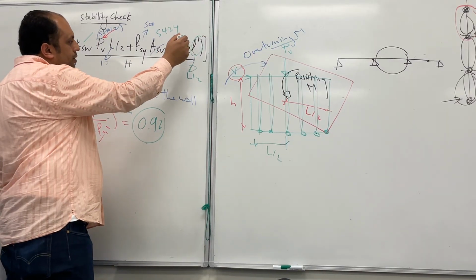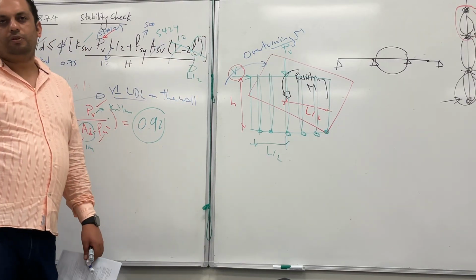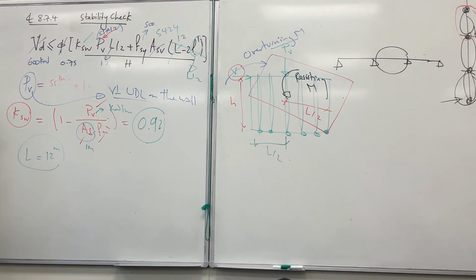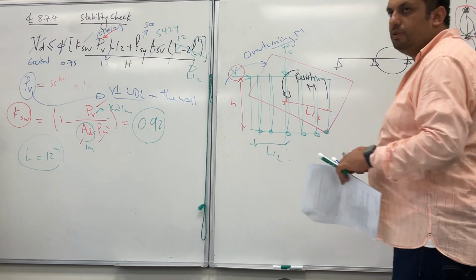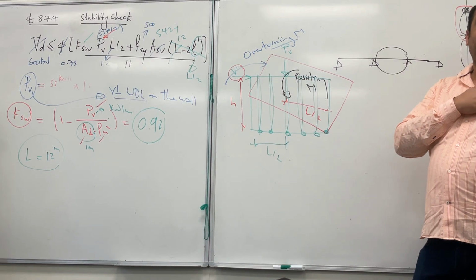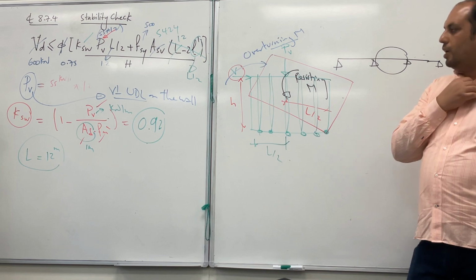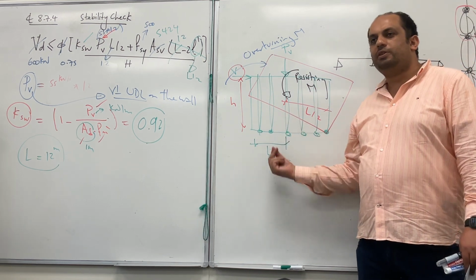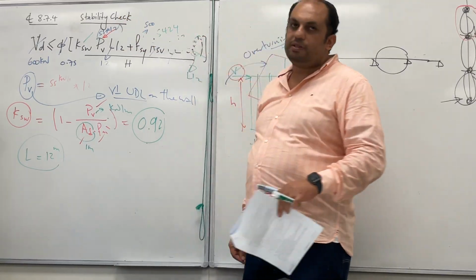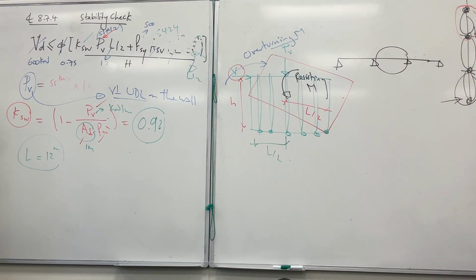So this means 12 minus 6, this will be 0. If you remember last time in the example, we mentioned that if the CG of the steel is in the middle, it is not contributing to this formula. You remember that? Because this reinforcement is symmetrical; otherwise, if it is not symmetrical, it will work. Anyway, where is the centroid of the steel? In the middle. If we apply it in the formula, this term is useless. This means the steel is not adding any resisting moment. Okay, guys?